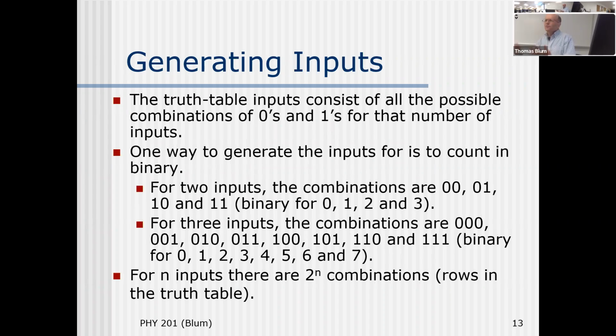Early on, in the first lab or two, I will emphasize this and say, what are the voltages, and are they high or low, and are they true or false? Later on, it'll just be ones and zeros, and we'll assume everybody gets it. But for a lab or two, here's a voltmeter, measure the voltages. Is that high or low? That depends on the context. The context is usually decided by the battery. If you put in a 5 volt battery, then 5 volts is high. If you put in a 12 volt battery, then 12 volts is high.